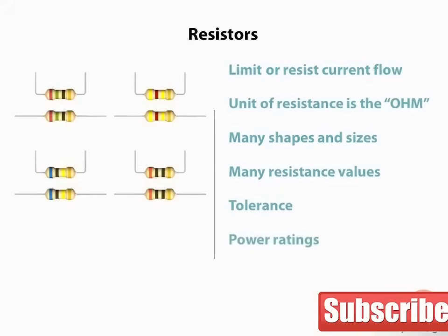One consequence of resisting current is that heat is generated. The heat generated can be expressed in watts, so a resistor that has a higher power running through it will be required to have a higher watt rating. Remember the power law? Higher power resistors are larger to dissipate heat, and some even have cooling fins. Choose a resistor that will handle the power it is dissipating.